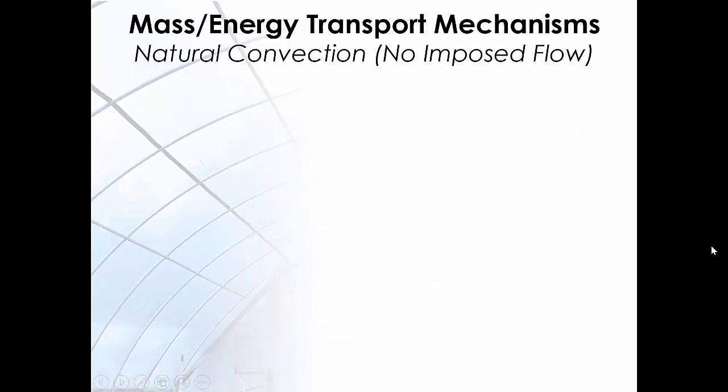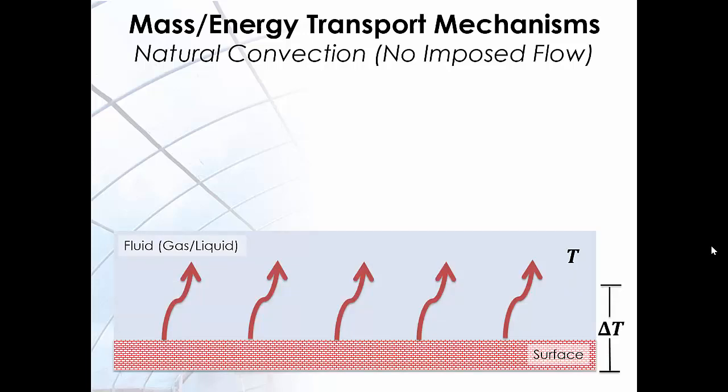In many cases, the flow may not be caused by external factors. Instead, temperature and concentration differences may cause the fluid to flow in a convection, and this is called natural convection. In the case of energy, determining the convective transfer coefficient is still possible through the Nusselt relationship, except there is a necessity to include a number that would characterize the temperature difference in the flowing medium.